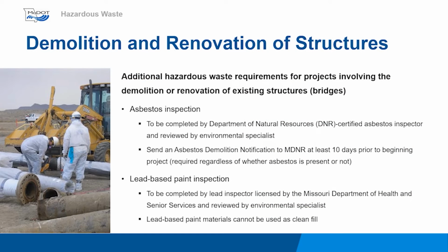Additional hazardous waste requirements exist for projects involving the renovation or demolition of structures. Most commonly, these requirements pertain to bridge rehabilitation and replacement projects. All projects involving the demolition and renovation of structures require an asbestos inspection and lead-based paint inspection. These inspections must be completed by qualified individuals who have valid, up-to-date Missouri DNR and Missouri DHSS certifications.